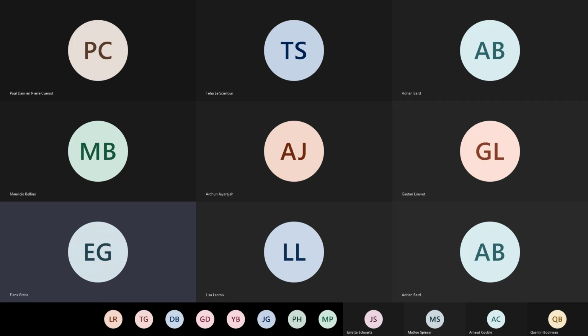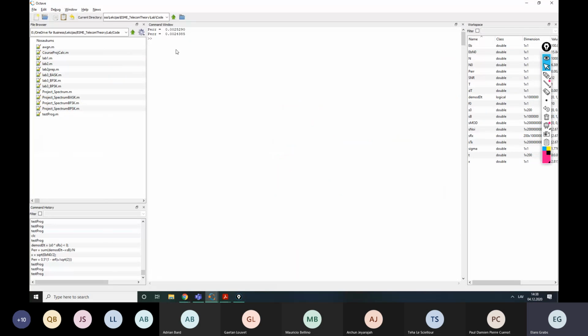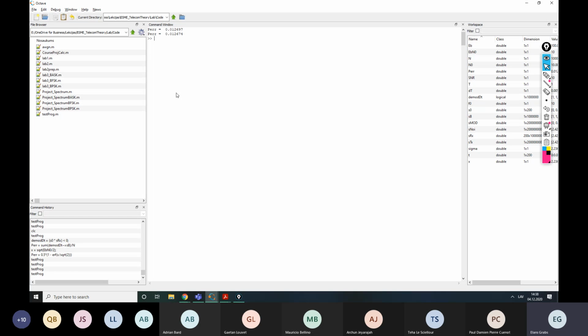And welcome back. So yes, let me repeat that, actually. I have checked the problem with signal to noise ratio, and there is no problem, because the simulated error probability value is very similar to the theoretical. We can change that signal to noise ratio, for example, to 10, simulate the script again, and it will increase the error probability, and they should be closer to each other. And indeed, we can see that these values are now closer.